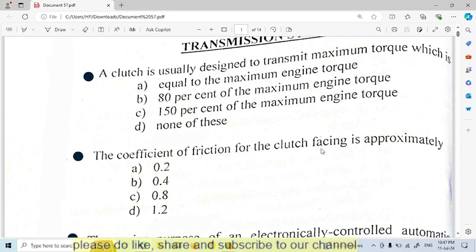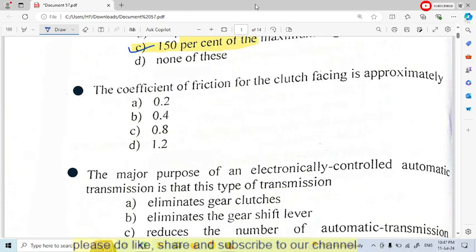So here is the MCQ. We practice the MCQ. The first question is: clutch is generally designed to transmit maximum torque, which will be 150% of the maximum engine torque. So option C is the correct answer. Next, the coefficient of friction for clutch facing is approximately 0.4. Option B is the correct.